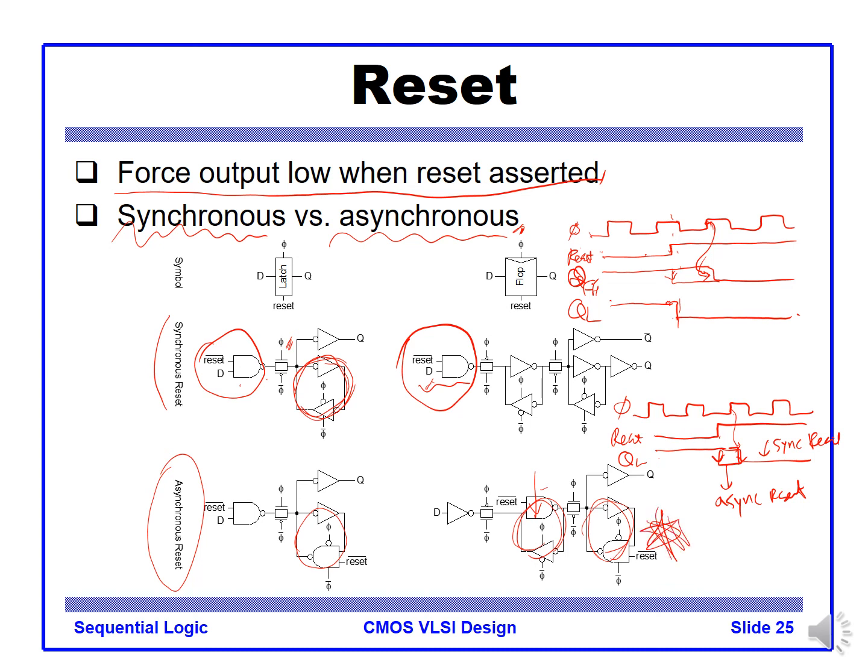Students neglect to reset the internal core when implementing an asynchronous reset. For power on reset or whatever, most resets are implemented asynchronously, so that it ensures the internal memory is all flushed out and cleanly reset. So this is important.